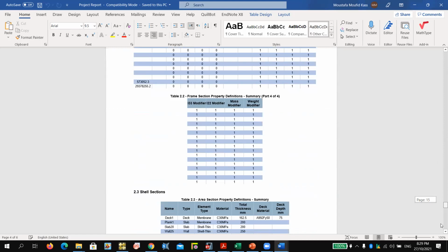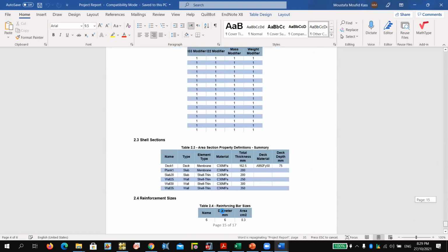So this is the summary of the report, which can help you go and write something. The important things are to know the short-term deflection, long-term deflection, the sway, the drift, and the axial forces on the columns. And if we have beams, we can do the same for the beam, depending on what comes with the beam.